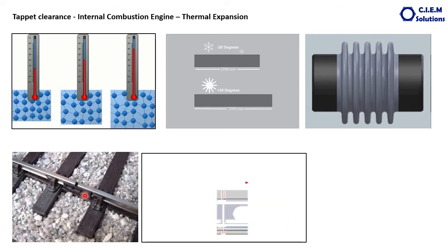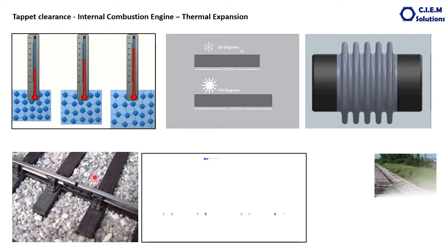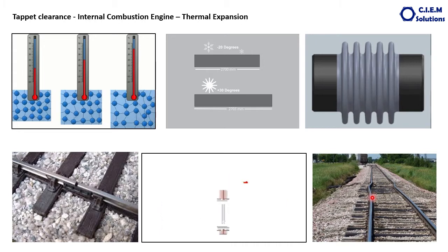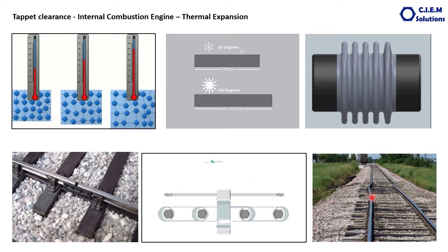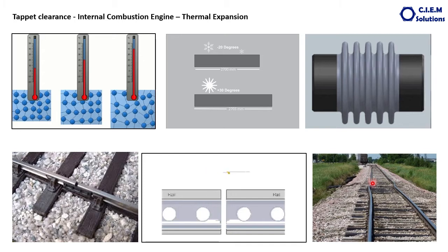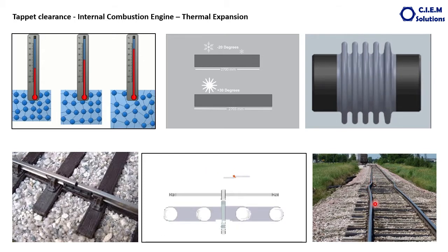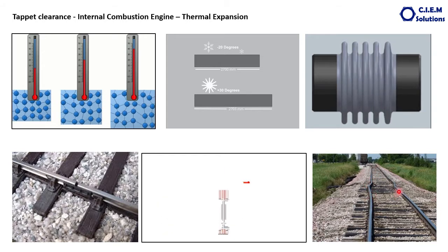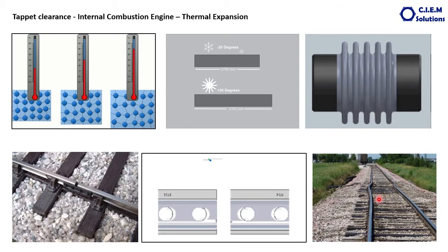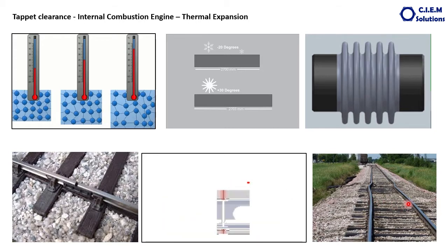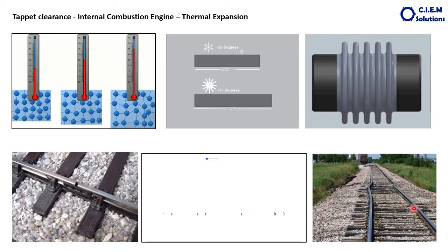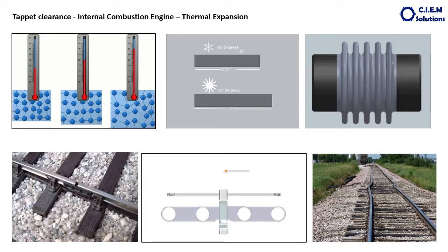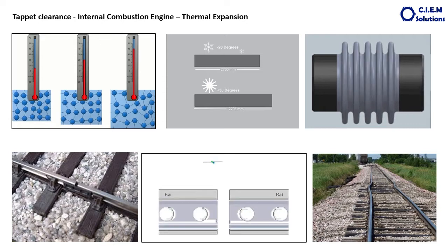And if we do not provide this gap, there is no space for the expansion. So to accommodate the increased length, these rails try to get deformed like this. This is a kind of deformation. When this deformation takes place, the uniform distance between these two rails, which is most important to run the train, is disturbed, so there is a possibility of the train collapsing.